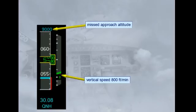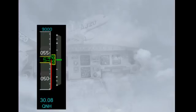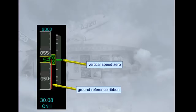Notice that the vertical speed indication is showing a rate of descent of 800 feet per minute. Also notice that the missed approach altitude has been set at 9,000 feet. When the aircraft lands, the ground reference ribbon is in the middle of the scale, and the vertical speed indication is at 0.